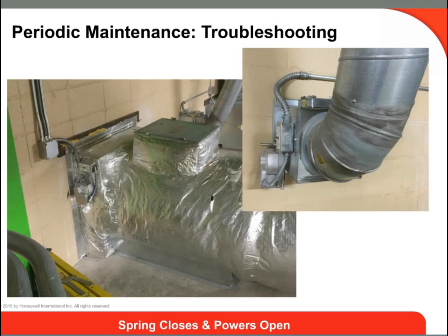If a fire and smoke actuator does not function, begin troubleshooting by checking that the appropriate power is being supplied to the actuator. This should drive the damper blades open. Also verify that the actuator is correctly mounted to the damper blade shaft so that the blades move when the actuator operates. If the blades touch the frame, verify that the frame is not racked.